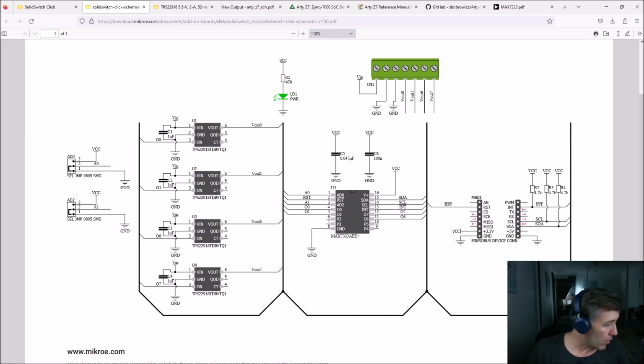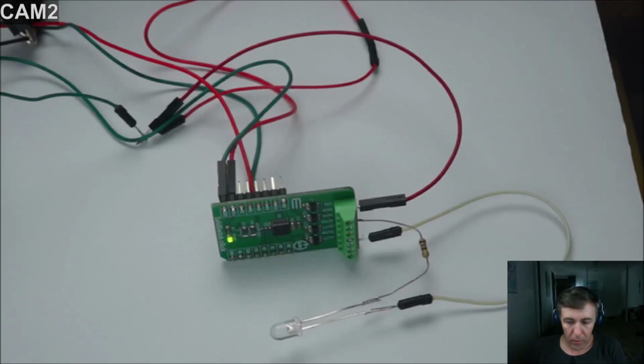So let's check the setup, whether we can get some results. So at this point our I2C interface is not functioning, probably due to multiple issues. Could be on the software side, could be on electronical side. Let's try to hook up an oscilloscope and see if we can observe toggling signals on I2C interface.